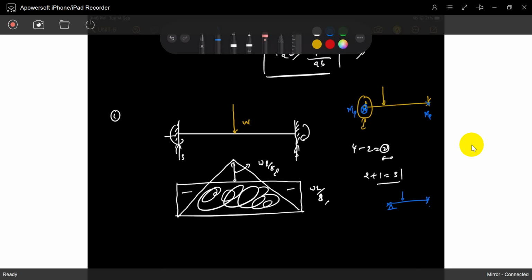Again the load is increasing, it reaches the MP state. So now it forms a simply supported beam. There is no indeterminacy, but it is still following the static theorem. It does not enter into the mechanism. Later, if you increase again,